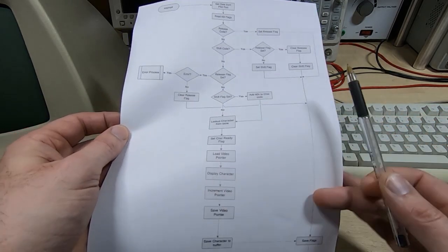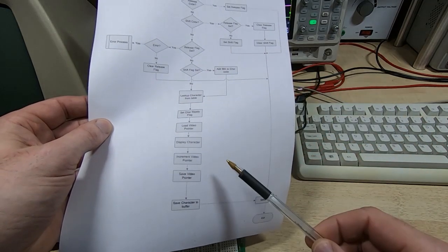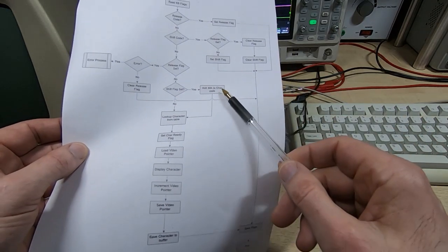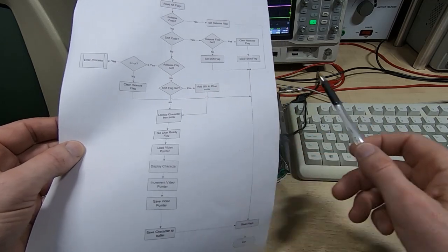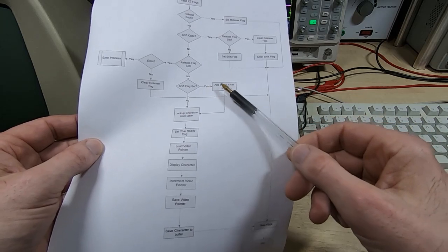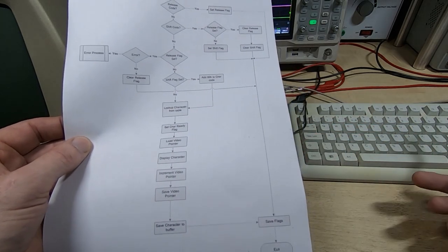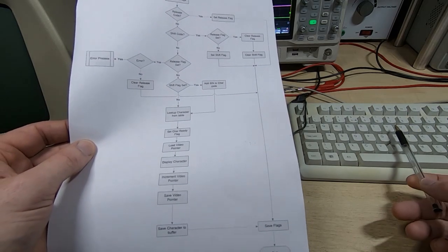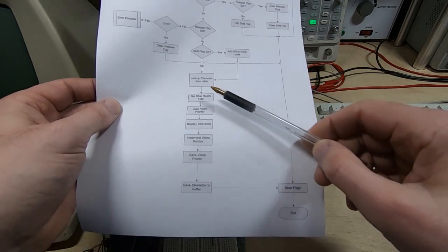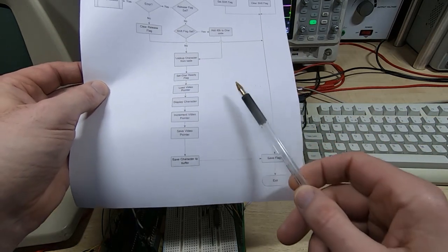And we'll have a look at this on the screen in a few minutes. And then it goes on to process the character that's been received. If the shift key has been pressed first, we're going to shift mode, in which case it modifies the pointer into the lookup table that it uses to convert between the PS2 scan code and ASCII code, and then it will go through and do whatever it needs to with the character.